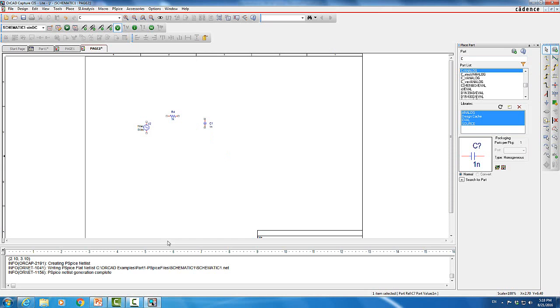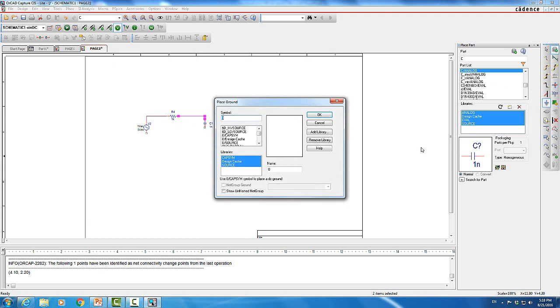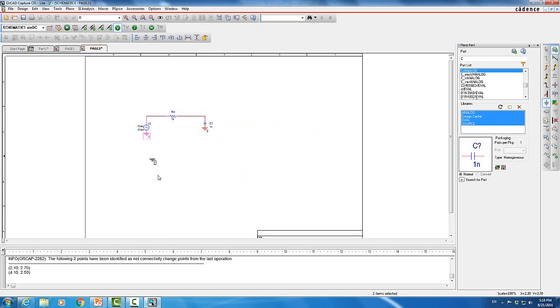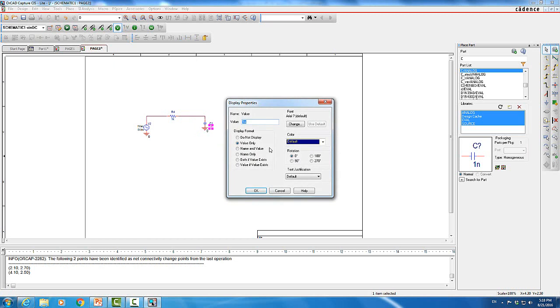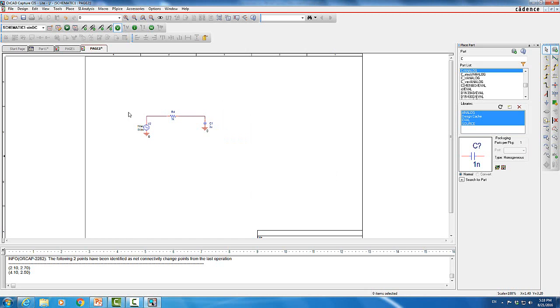So now all we have to do is connect those elements together. I'm gonna go from the voltage source into the resistor to place a wire, and then from the resistor to the capacitor. Make sure you place a wire, which is different from those ones, and this is a bus, which is totally different. The wire will be the thin icon over here. And then we're going to add the grounds. The ground we're going to use is the CAP SIM, and we place a ground here and a ground here. And finally, the value of the capacitor, I'm going to make it around 3 micro Farad. So we're going to have 3U, which stands for 3 micro. Click OK. And basically the circuit diagram has ended.